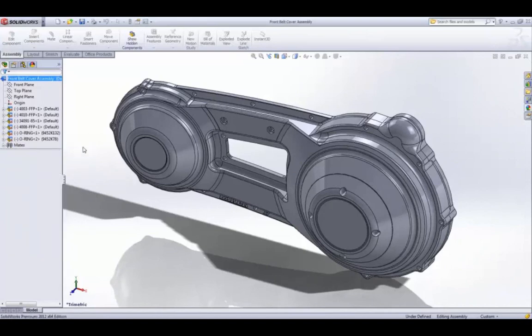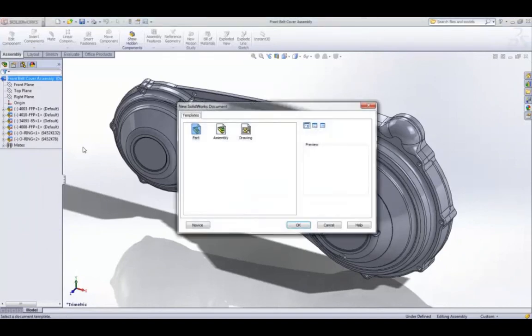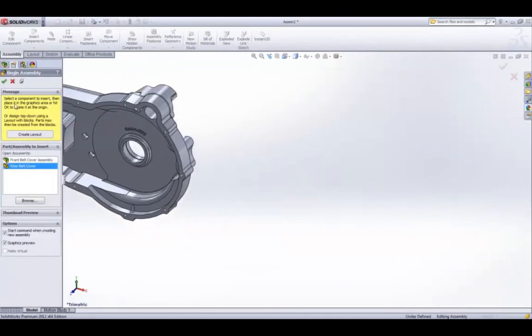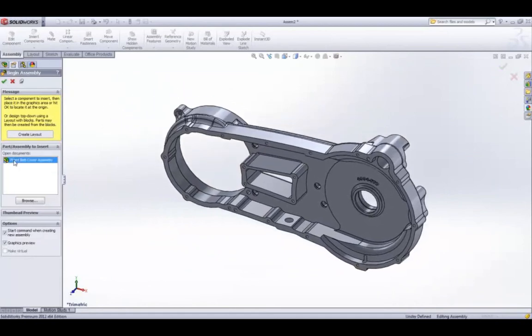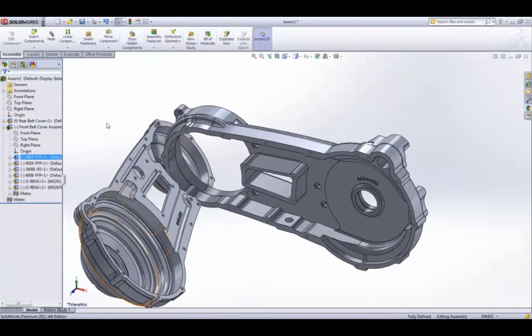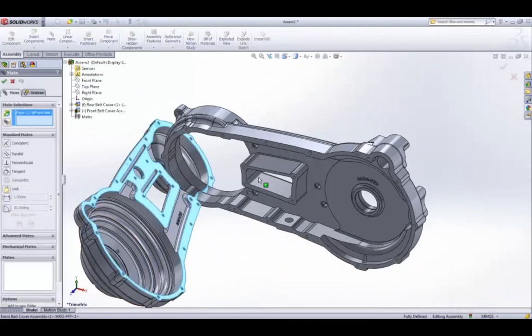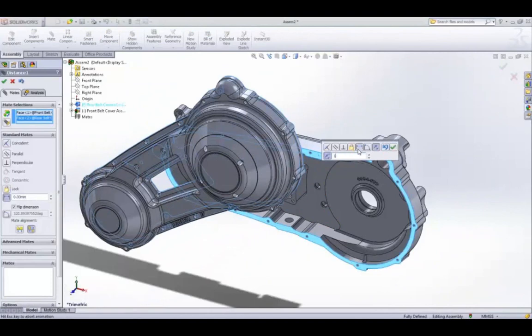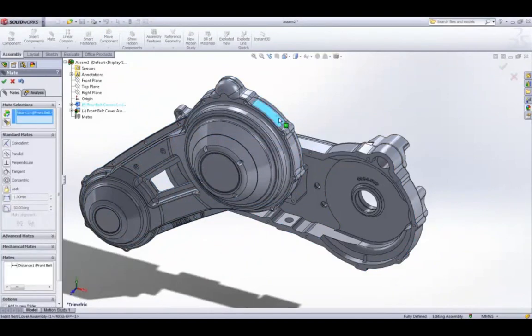So, how does the user using 2012 benefit from this? In our case, we need to design a new gasket, so let's start a new assembly. Immediately we can see that we can insert 2013 files we currently have open in our 2012 assembly with no hassle. We can interact with these much like we would any other file inside 2012. In this case, we'll add a few mates to position these components properly. You'll notice we can mate to geometry or planes or origin if desired.